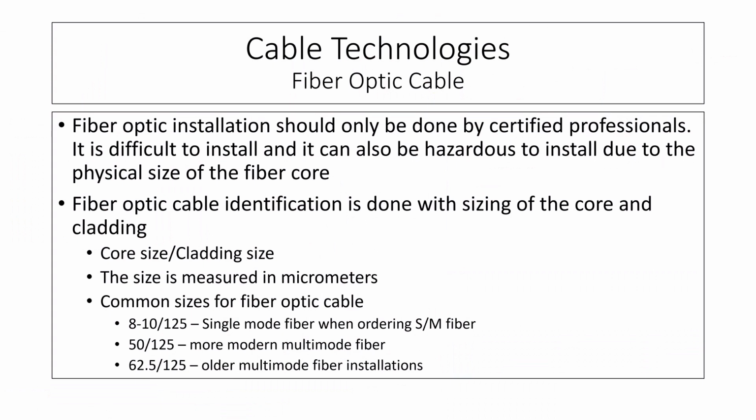When dealing with fiber optic cable, especially for installation within walls, use certified professionals. This is extremely difficult to terminate properly, and you want it done by professionals. Also, installing fiber optic cable can be hazardous due to the small size of the fiber optic core. If it were to get into your bloodstream, it can actually cause damage, and it can fit in capillaries. These glass pieces are very, very thin. Always have a professional install your fiber optic cable.